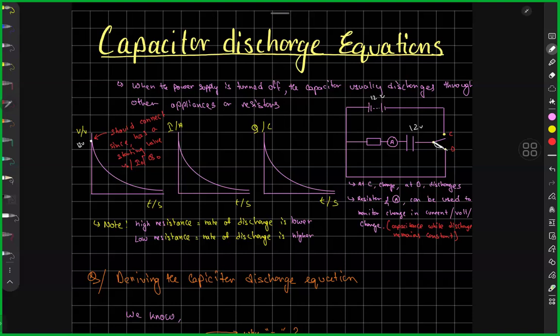Good. Right? And this part should be connected to the y-axis. Always remember that. Why? Because it is a known value. It is not going to be an asymptote over here. Nope. It is a known value. It is at time equals 0. It is not infinity. It is 12 volt. So this part of the curve should always meet the y-axis. Always remember that.